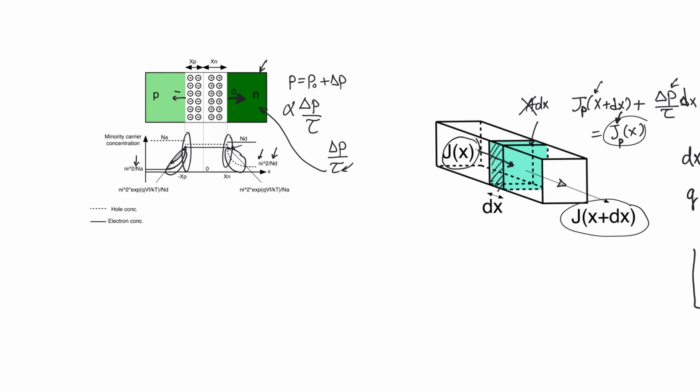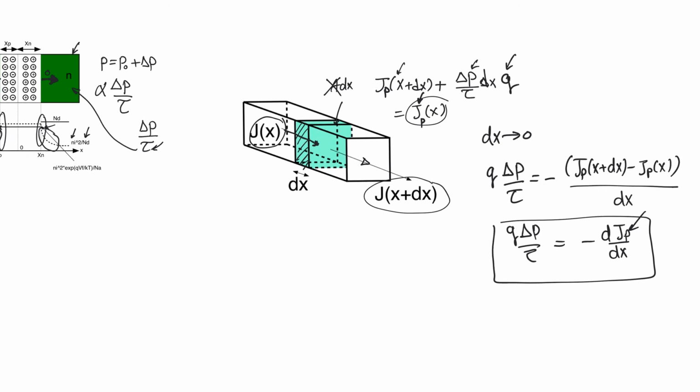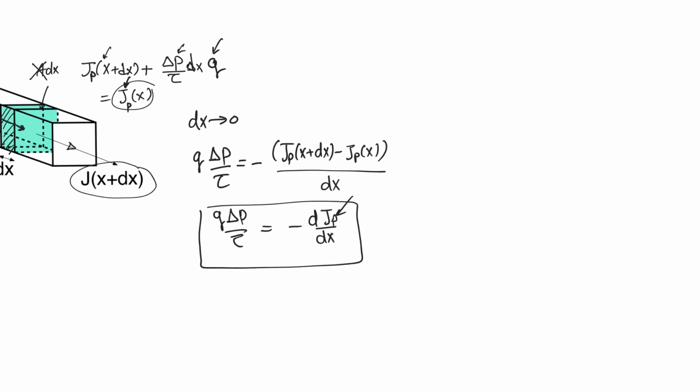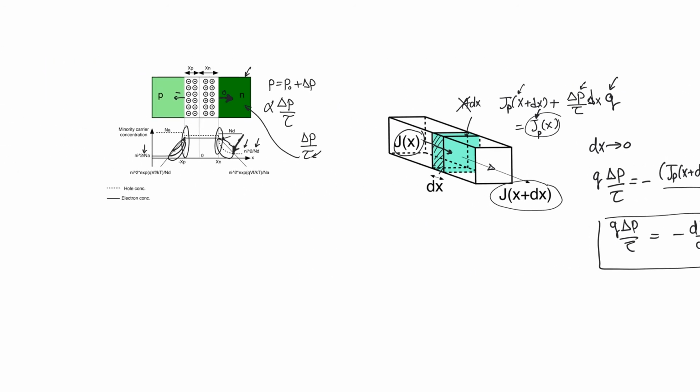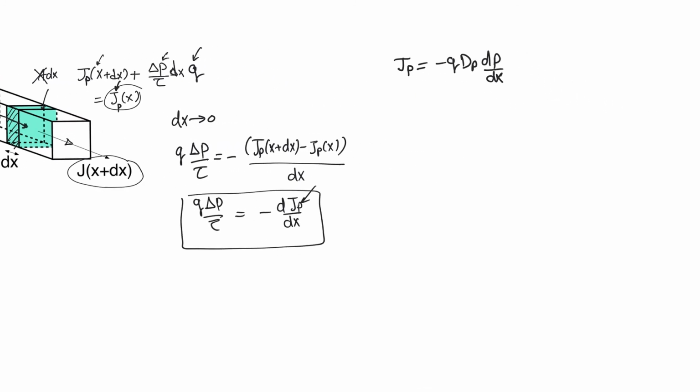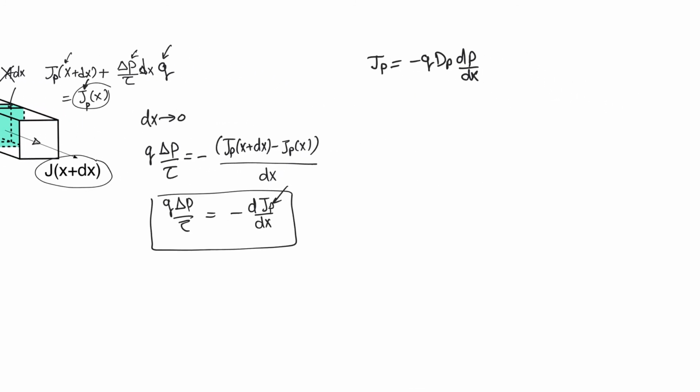If you recall, when we apply a forward potential, we lower the potential barriers for majority carriers on each side, allowing them to inject a lot of minority carriers onto the other side, which happens by diffusion. So this is a diffusion current. If we write the expression for hole diffusion current, it's minus q dp by dx. dp by dx is the gradient of the hole distribution profile, which if we look at the n side, is actually a curve and has a finite gradient for a long distance. So there is a diffusion current within the n side.